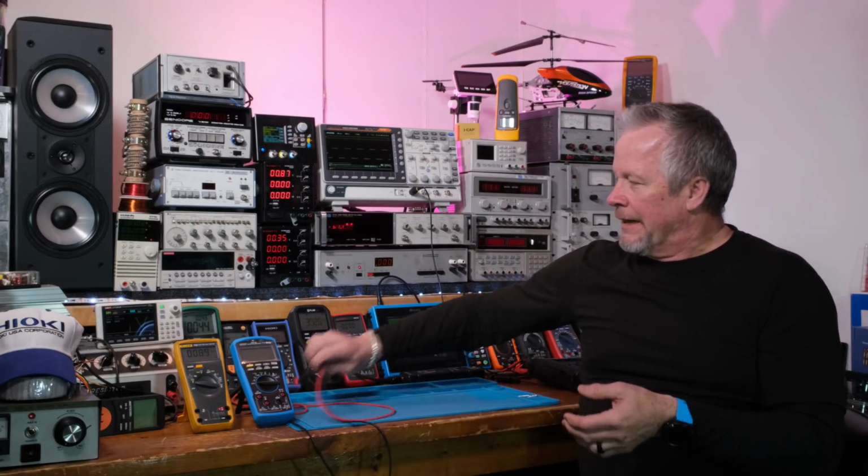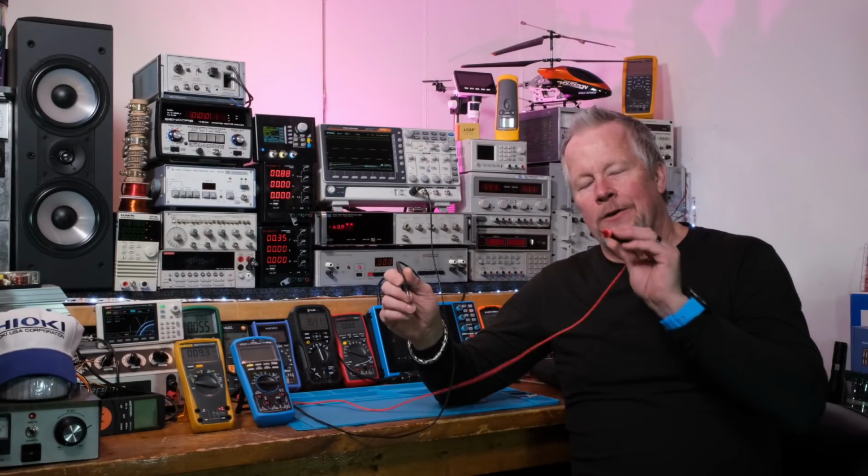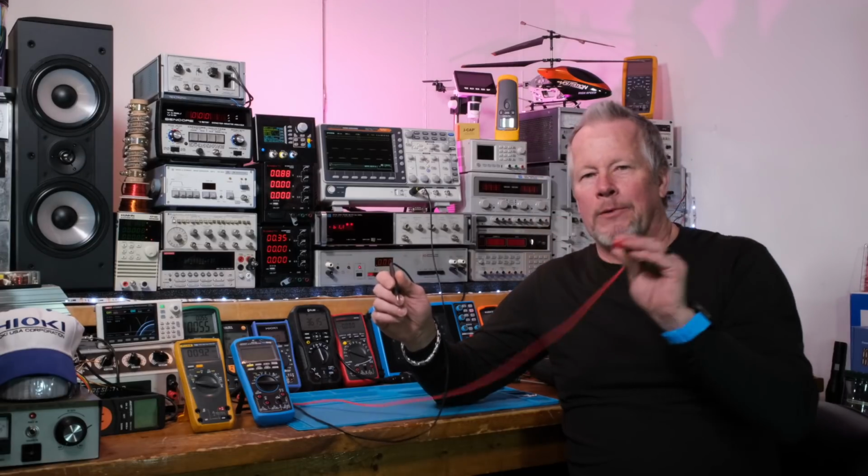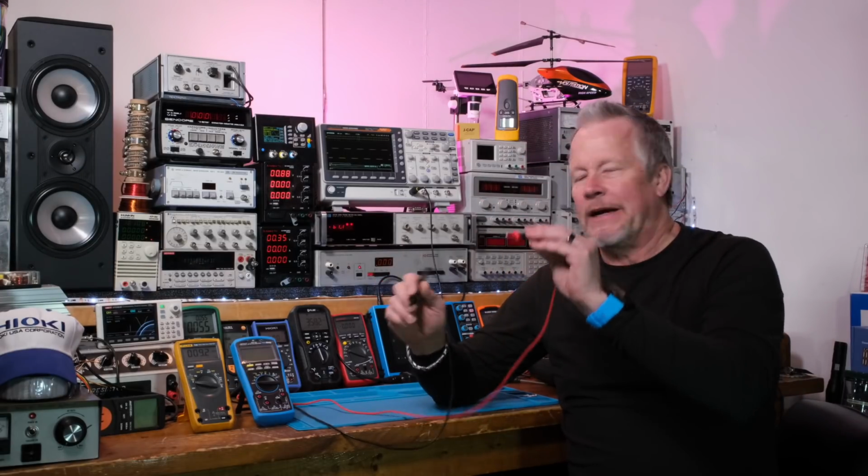It's kind of showing the ground is just a reference point. It doesn't have to be 0 volts. It can be any voltage. And whatever voltage that happens to be, if you're saying ground is 0, that's my 0 reference. So when I put my black probe on ground, in this example plus 6 volts, and I take this probe and probe around, I'm going to read minus voltages, right? So it's just a reference.